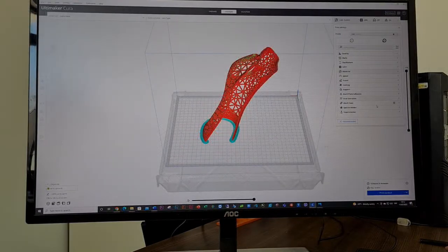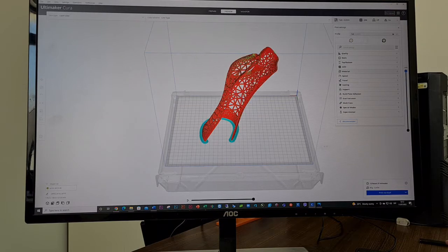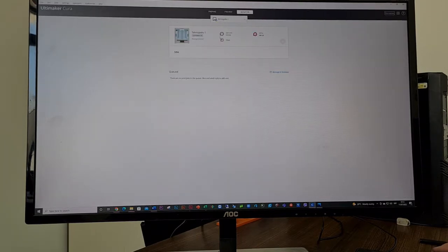When we are satisfied with all printing parameters, when we visually confirmed that our project will end up with high quality, as well as time consumption and consumption of raw material, we can print it with USB card, directly putting into the 3D printer, or we can print it via cloud. This is very important option which enables us to control our printer remotely.